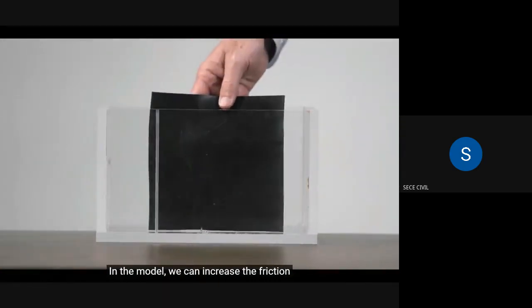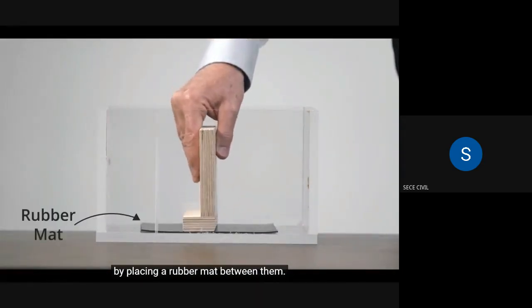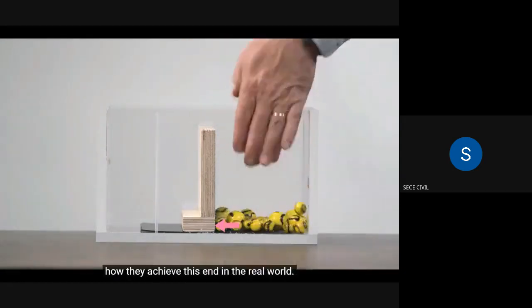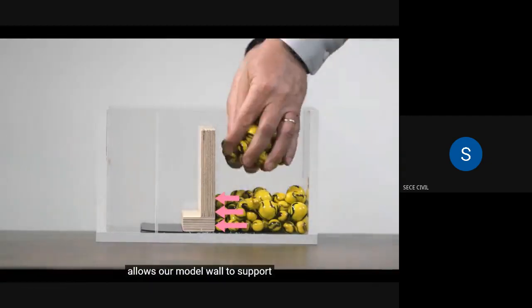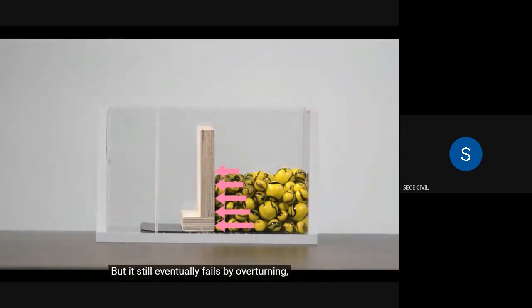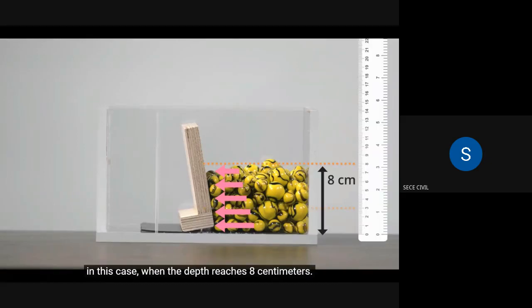In the model, we can increase the friction between the retaining wall and the base by placing a rubber mat between them. You will have to do some extra reading if you want to find out how they achieve this end in the real world. As you can see, increasing the friction allows our model wall to support a noticeably greater depth of marbles, but it still eventually fails by overturning, in this case when the depth reaches 8 centimeters.